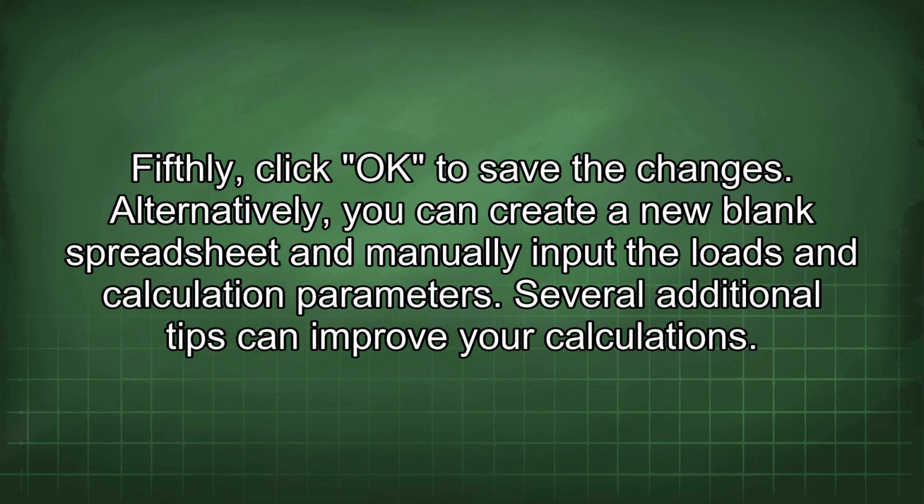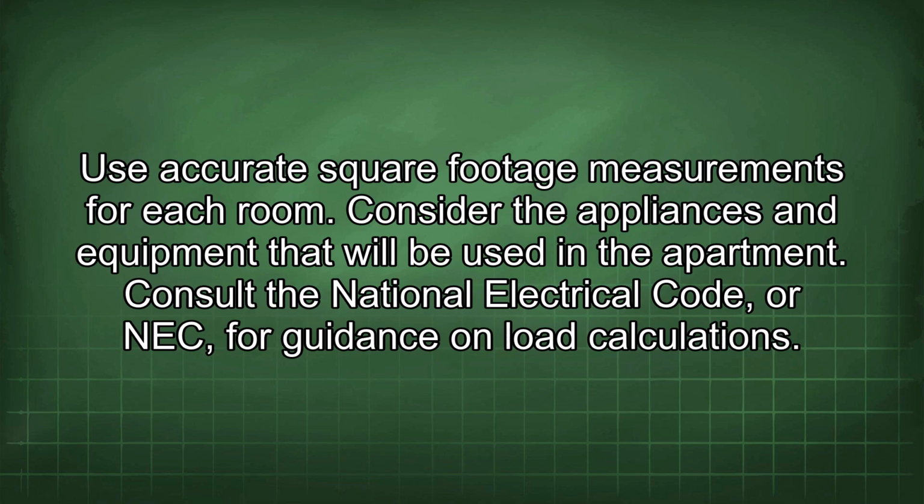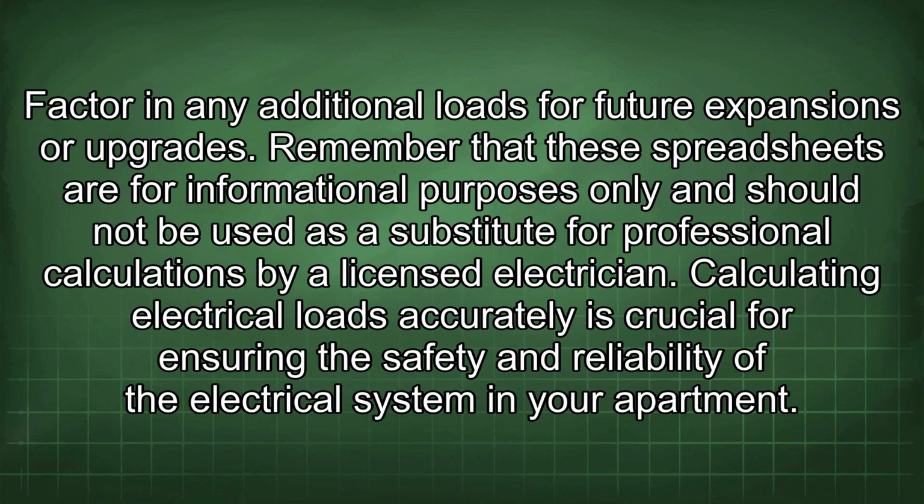Several additional tips can improve your calculations. Use accurate square footage measurements for each room. Consider the appliances and equipment that will be used in the apartment. Consult the National Electrical Code, or NEC, for guidance on load calculations. Factor in any additional loads for future expansions or upgrades.